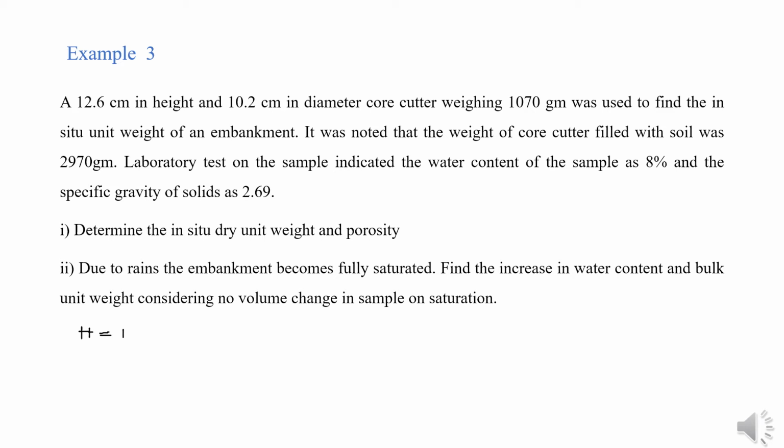So let me write the height as h, given as 12.6 centimeter. The diameter, let us represent by d, is given as 10.2 centimeter, right? So we know the height and the diameter. The core cutter is a cylindrical apparatus, basically a metallic cylinder. So the volume of the core cutter gives the volume of the soil sample.